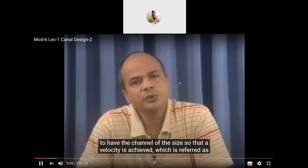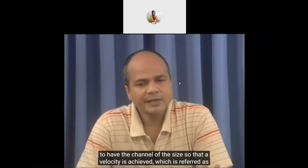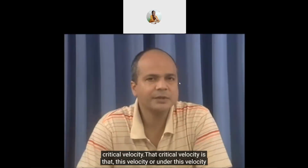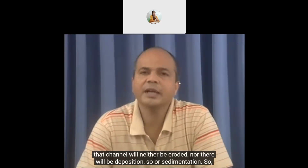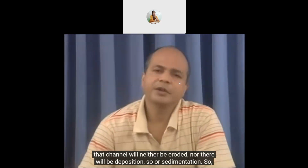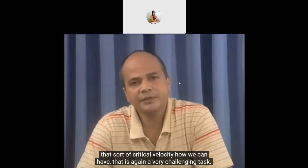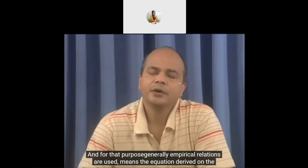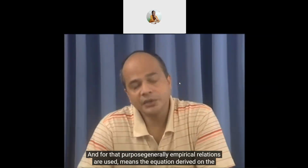Generally people try to have the channel of a size so that a velocity is achieved which is referred to as critical velocity. Under this velocity, the channel will neither be eroded nor will there be deposition or sedimentation. How we can get that sort of critical velocity is again a very challenging task, and for that purpose empirical relations are generally used.